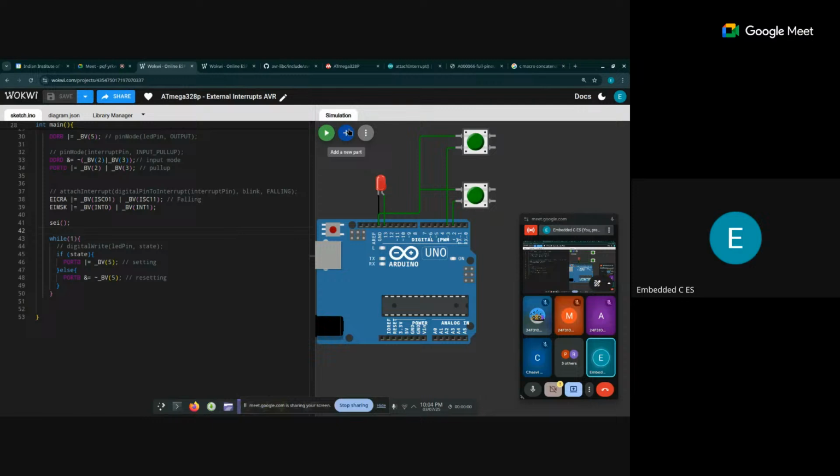Assume you have a count variable and you are doing some task with it. If an interrupt happens in between and that count variable gets changed, the variable will change in the middle of the calculation, right? So in that case, before doing such operations, we clear the interrupts, do that operation, then enable the interrupts back. In those cases, SEI and CLI would be useful.